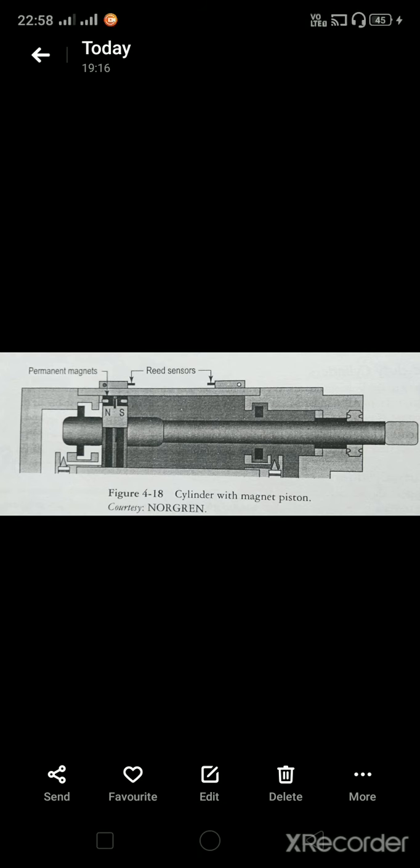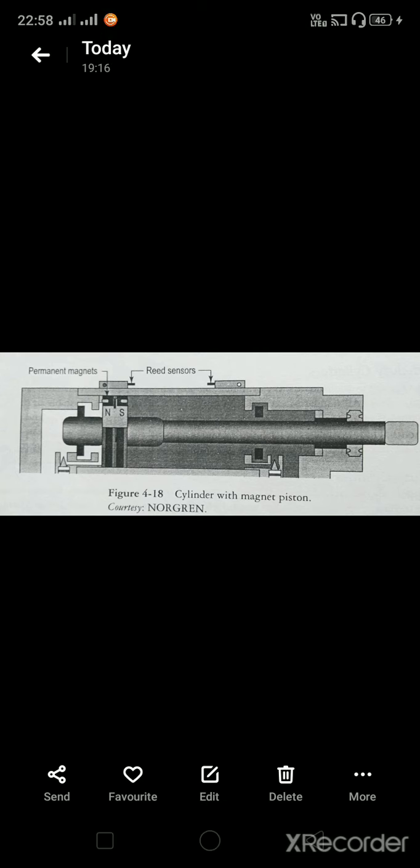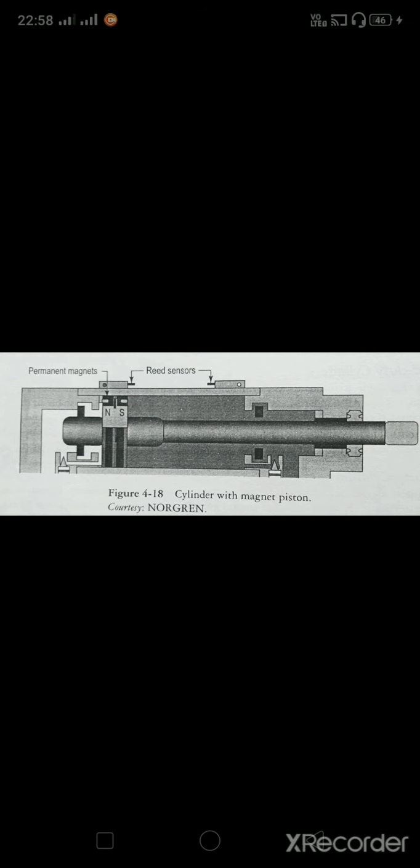The cylinder with magnetic piston, when used in conjunction with magnetically operated switch valves, will provide electric pneumatic output signals which can be used for many industrial applications. These cylinders have a number of advantages over conventional trip switches, valve switches, etc., providing a compact installation and supporting a neater appearance at a very low cost.